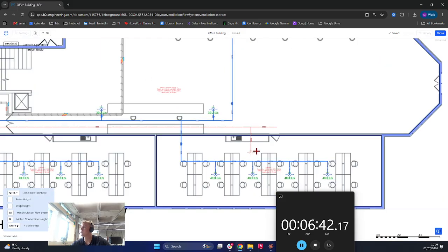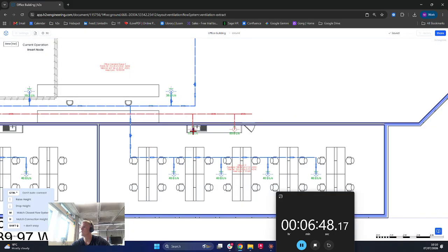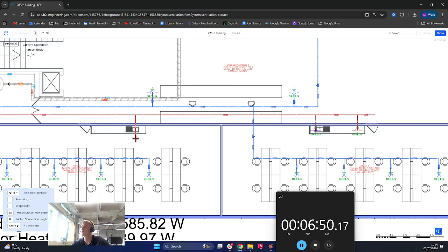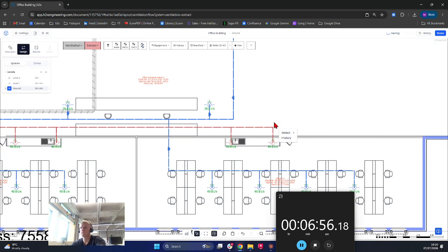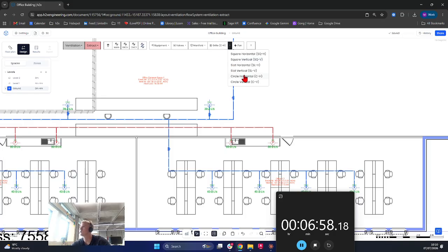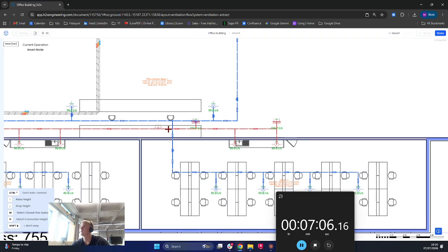And then we can select our circle horizontal diffusers, place them into the T-points here. I'm going to place 2 for every T-point. And then I'm going to select some circle or some slot vertical diffusers here to take out the extraction flow rate from this level.